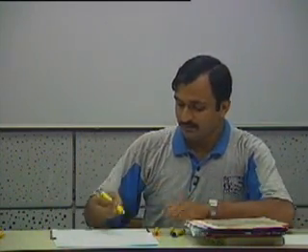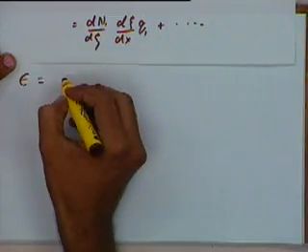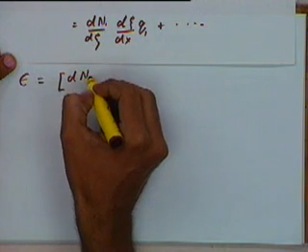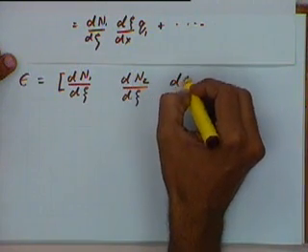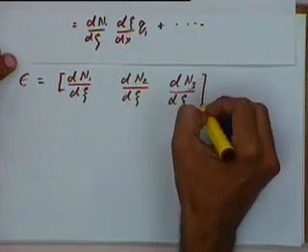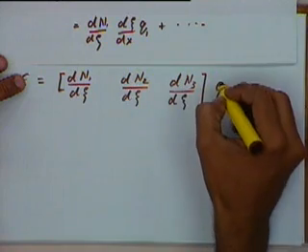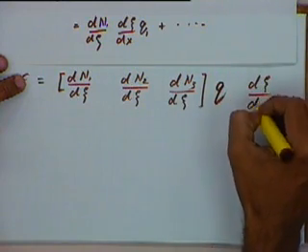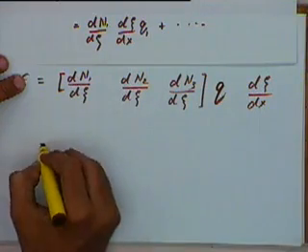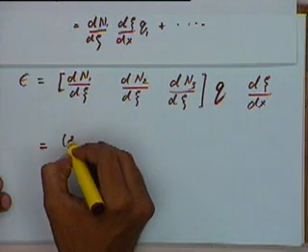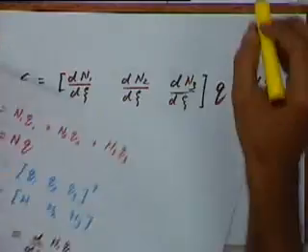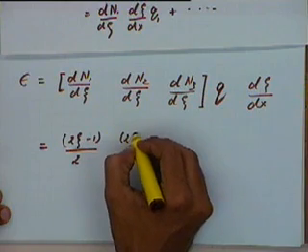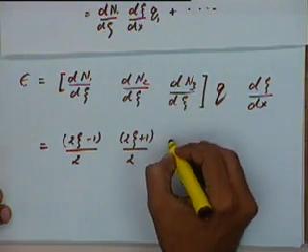So from this we will get epsilon, let me write it again in matrix notation, multiplied by q and of course multiplied by d zeta by dx. dN1 by d zeta we take from there, it will be 2 zeta minus 1 by 2. dN2 by d zeta is 2 zeta plus 1 by 2, and dN3 will be minus 2 zeta.